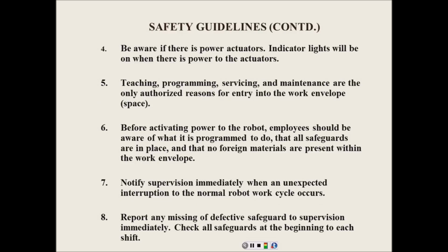Be aware of your power. Y'all have seen lockout, tagout. Do you understand that? Of course, we won't need to do that, because we're not doing any maintenance on these robots. But if you do the industrial class, we'll lock out, tag out. Our disconnects are capable of being locked and tagged. Most of them have like 3 locks you can put on there, and then that guy showed you how he has that extender you can put on there to put up to 8. And the locks have to be keyed. They can't be combination locks, because combinations get around, right? Keys don't. Well, that's not true. They shouldn't.